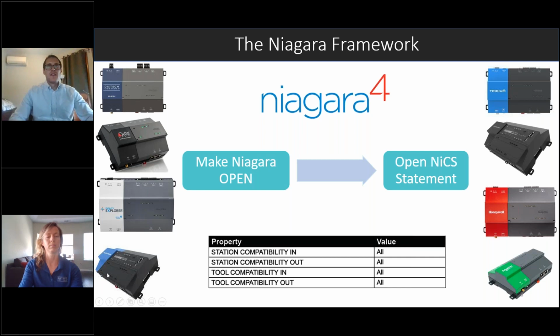So as you can see with the Niagara Framework, these JACE building level controllers I mentioned, that Java Application Control Engine, it's not just specific to any one vendor. A lot of the BAS vendors have their own form of a JACE. Nice fun different colors here, but they all operate the same way. They all still run that Niagara framework within them.